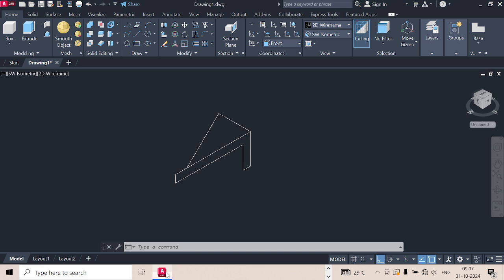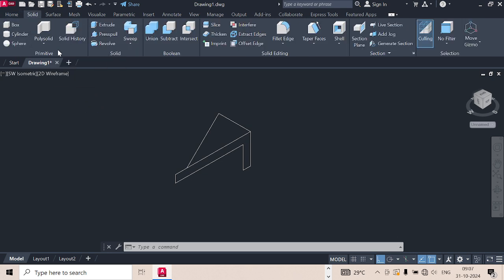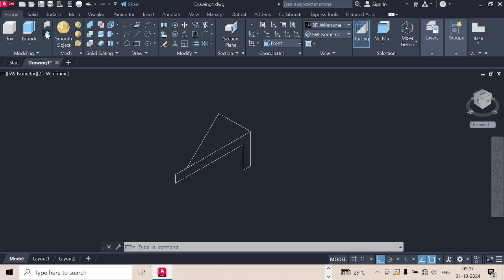Both profiles. This top one extruded, it is having same edge here, even though we can extrude this using press pull command. Okay, go for solid and press pull. Home also you are having that here, press pull, that command is. Take that command and the pick box will come. You select this area first.